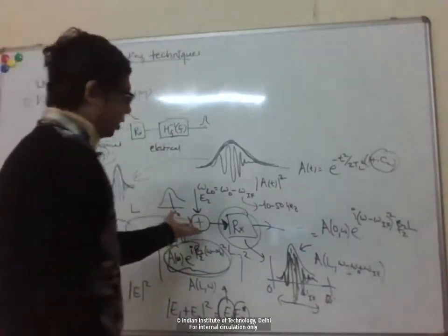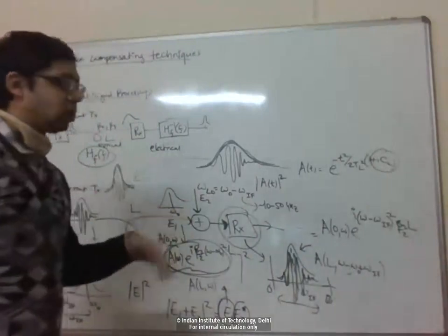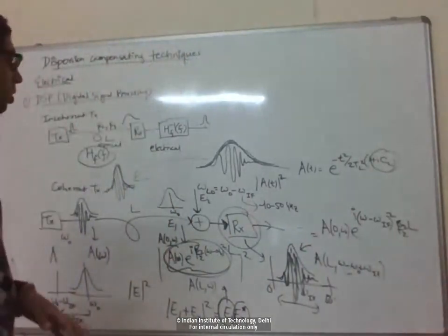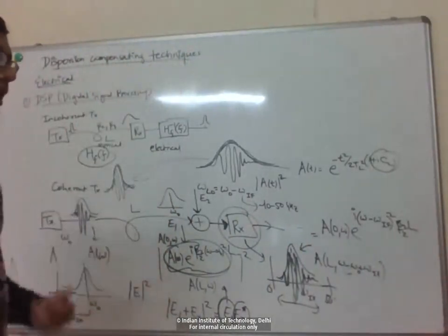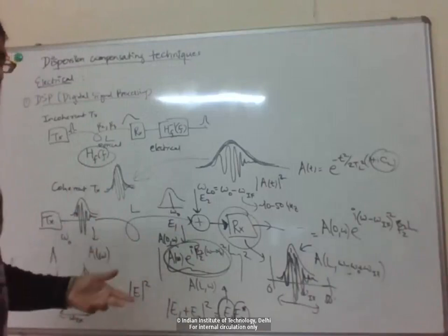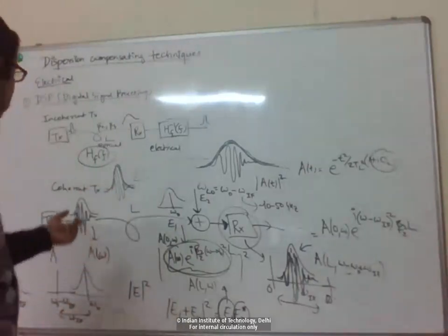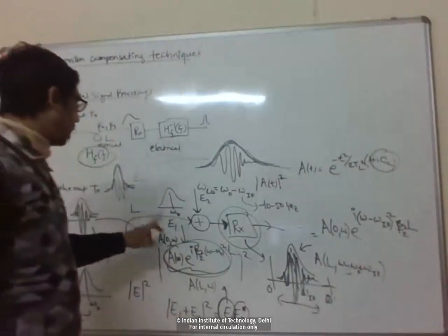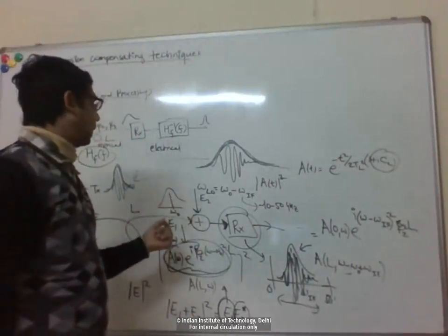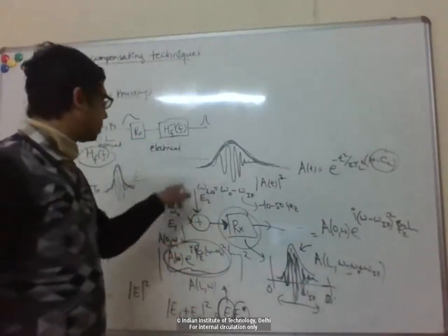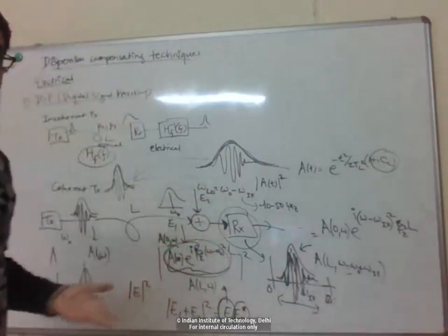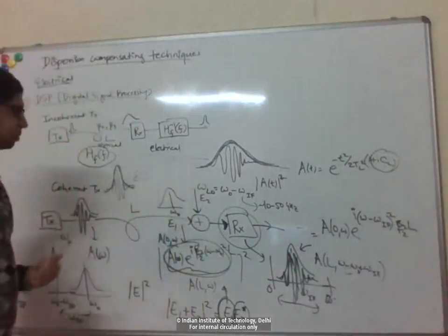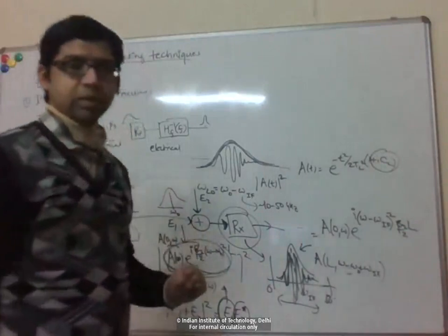So you can imagine you need this technique if, instead of the intensity, you encode the information in phase or frequency, right? If you have phase shift keying or frequency shift keying or more complicated modulation schemes like quadrature amplitude modulation, things like that, you cannot use just direct photo detection, because you need to recover phase information. So there also you use this beating with the local oscillator. This technique is called coherent detection for that reason, because it's used to detect coherent modulation schemes, where you also have phase information.